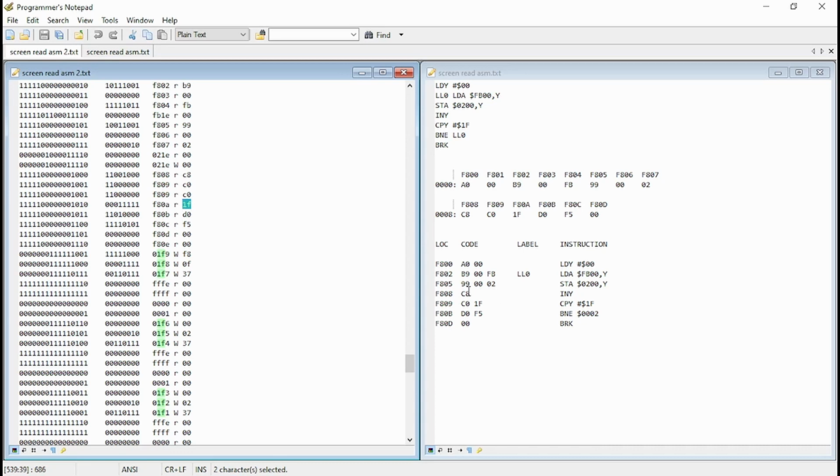So then what it does, FB says branch if not equal, so it's still reading those two, but we don't branch. We actually this time go to F80D, which is that one, we break, and interestingly it goes to the next line, which is also a 0, which we don't have in this code but in the hex, F80E, which is another 0. So again it's reading that one afterwards, which is slightly curious.